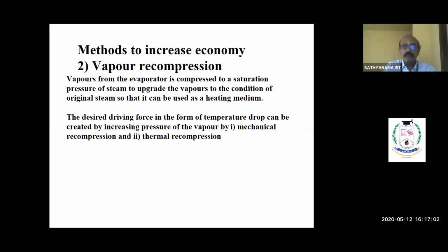So the vapor from the evaporator is compressed to a saturation pressure of steam such that the quality can be upgraded so that it can be used as a heating medium. Thereby we can improve the economy.